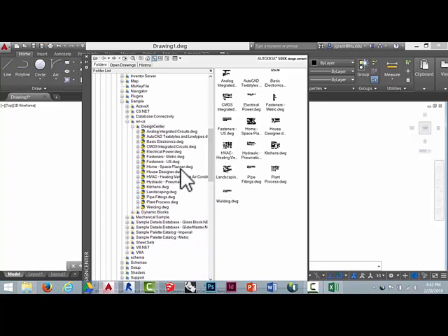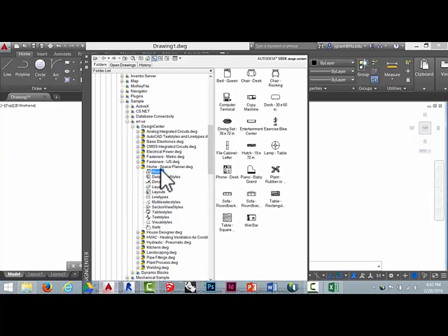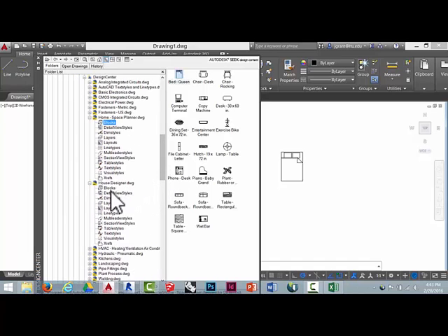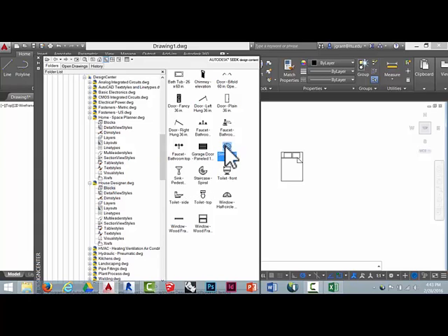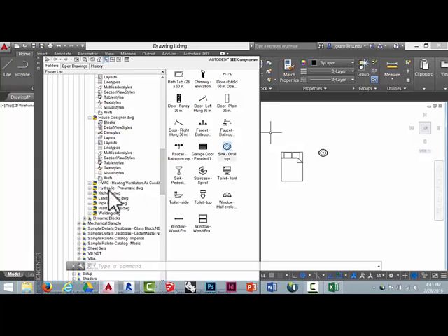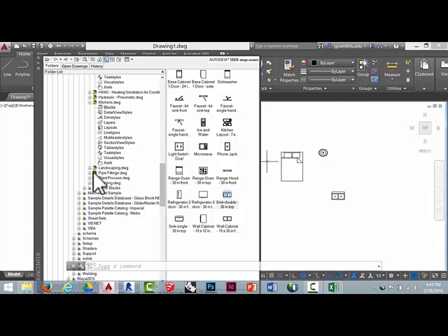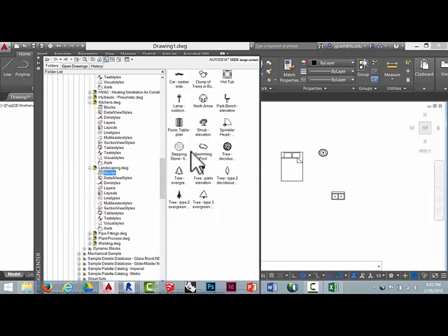And then in this Design Center, you have all of these different drawing files that have blocks inside of them. So you can go to the Home Space Planner and click on blocks right there. You can then drag and drop these drawings into your drawing. They're blocks that are inside a DWG file. And here in the Design Center, we also have House Designer, which has a few blocks like the sink and the tub. We also have some HVAC symbols, kitchens, landscapes. So if you wanted to, pull in a double sink or work with some landscaping, there are some trees here and north arrows here too.